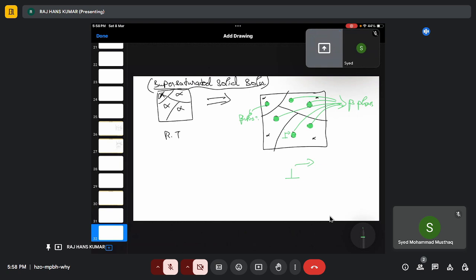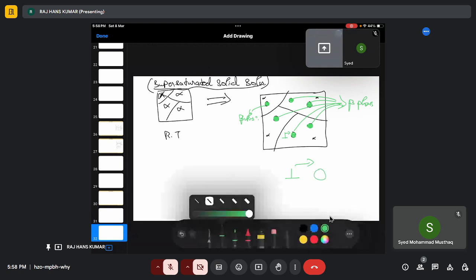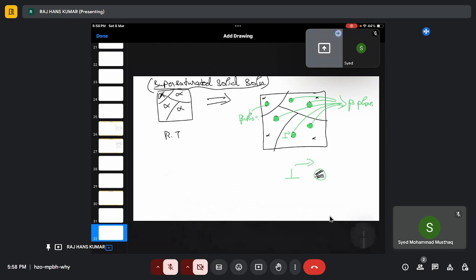If there is any obstacle, just like these precipitates, right? These precipitates have a different crystal structure also. If they are harder when compared to the alpha matrix, then these dislocations cannot freely move beyond the precipitate, and because of this there is an obstruction, or a stress field.